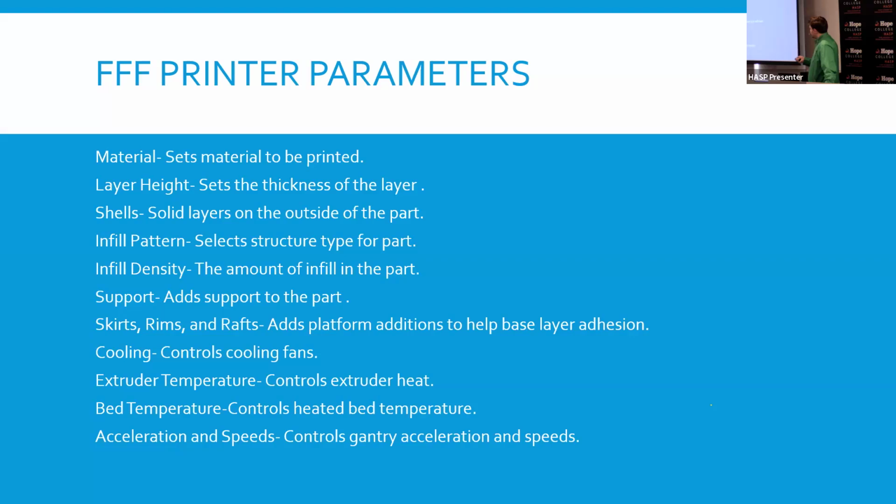So skirts, what they're going to do is create a square or a shape around the part. And what that does is it primes the nozzle and gets the material ready.